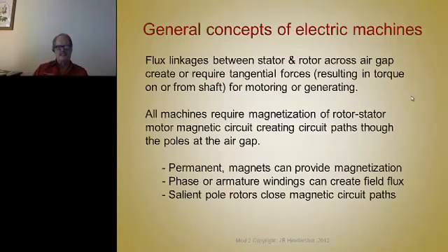It's really quite amazing that you can get so much force created in air, and it's the magnetic field that's created by either electromagnets or permanent magnets that creates that stress. If you look at the air gap stress in electrical machines, we're going to study that later, but the highest ones that I've ever seen put out 35 pounds per square inch of air gap stress.